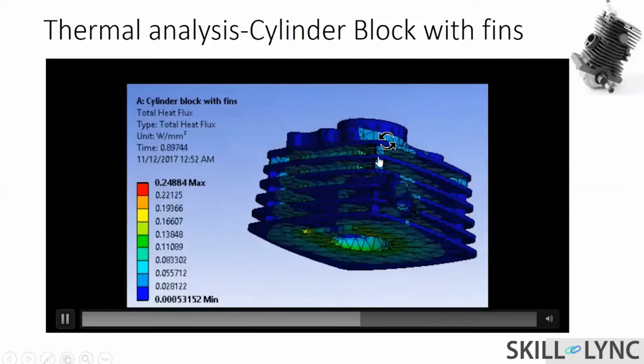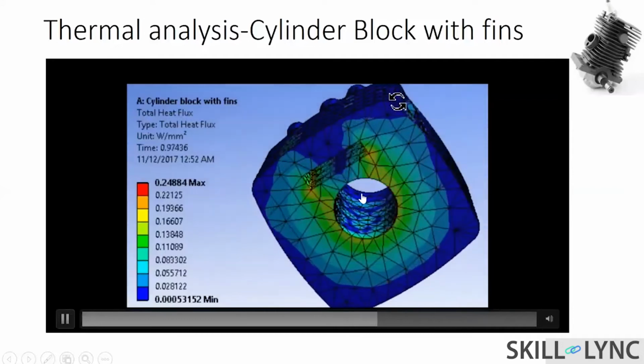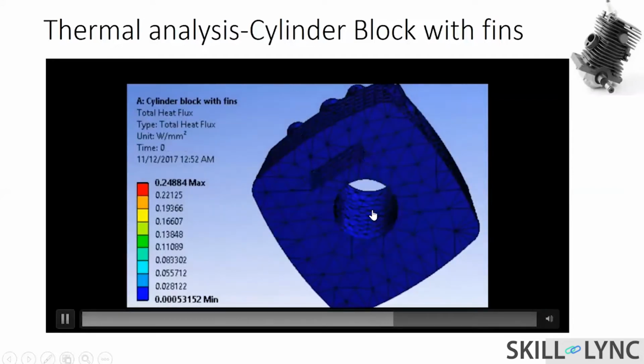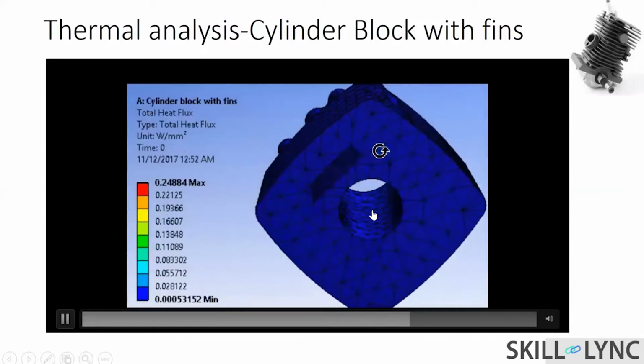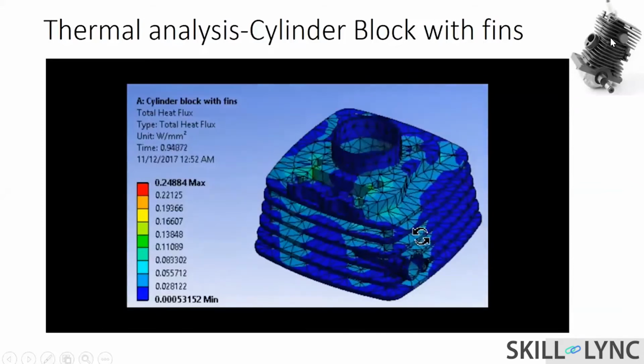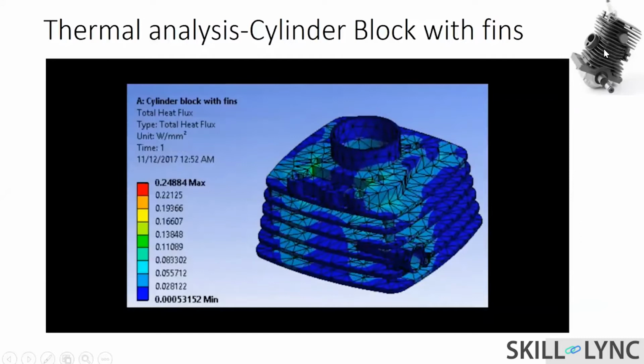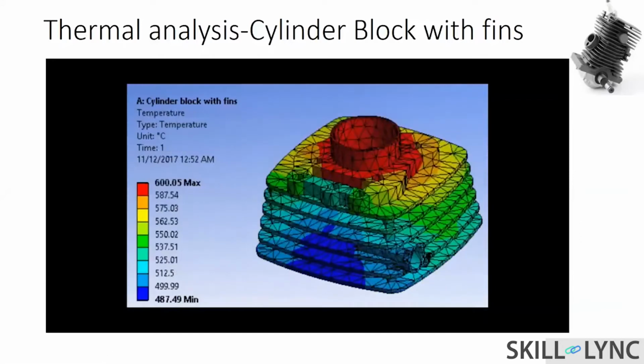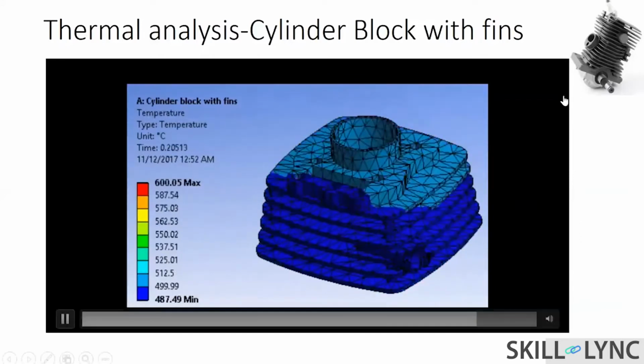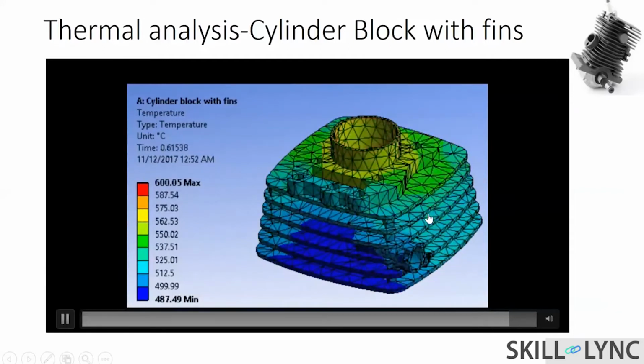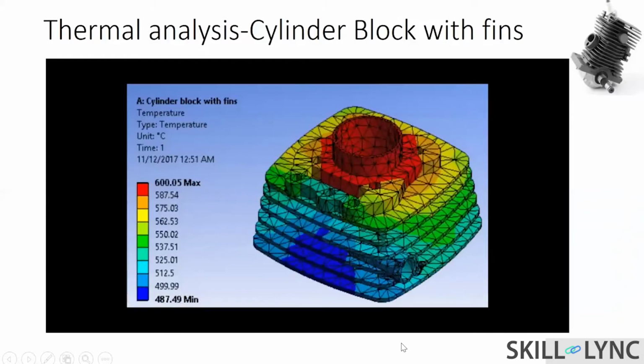In this case, we are saying that within this region is where combustion happens, and you're going to see how effective the fins are, how effectively they can transfer the heat from this region to the environment. So the importance of the fins would be discussed, and thermal analysis on the cylinder block would be carried out here. What else could we do?